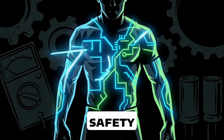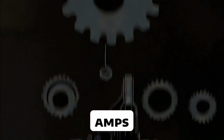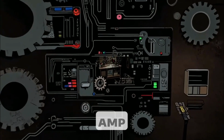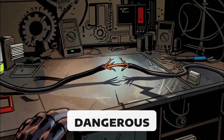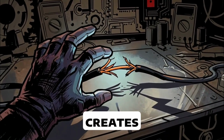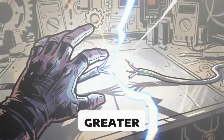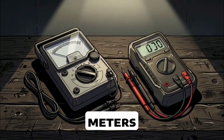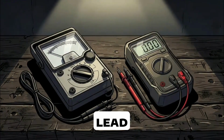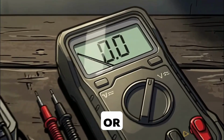A key safety fact: as little as 0.050 amps, 50 thousandths of an amp, can cause severe pain. Even small current can be dangerous. Voltage creates the push for current through the body, so higher voltage usually means greater shock risk. The chapter covers analog and digital meters. Depending on settings and lead placement, 1 meter can act as a voltmeter, ammeter, or ohmmeter.